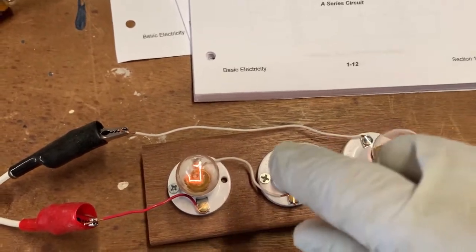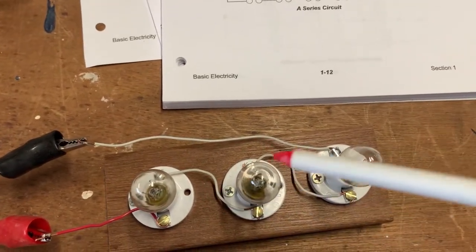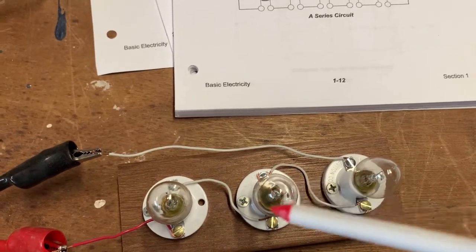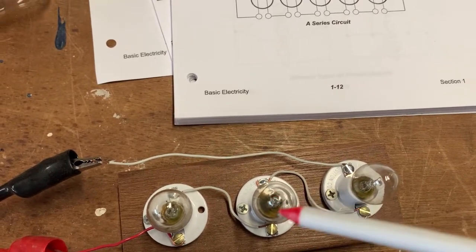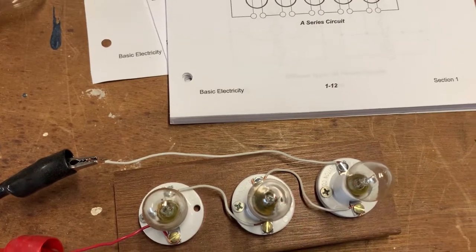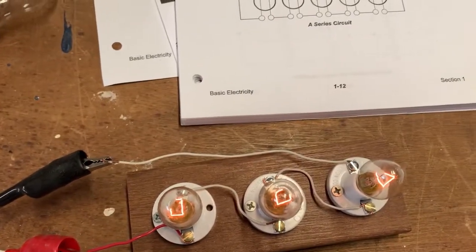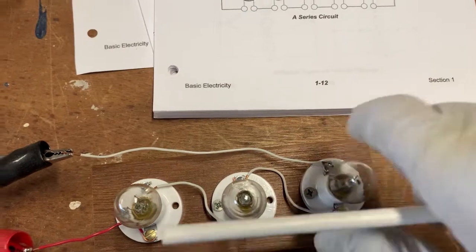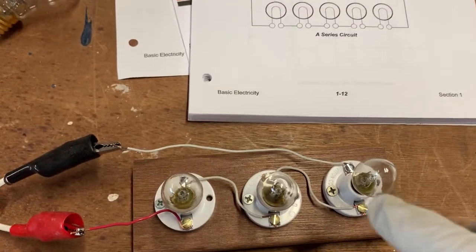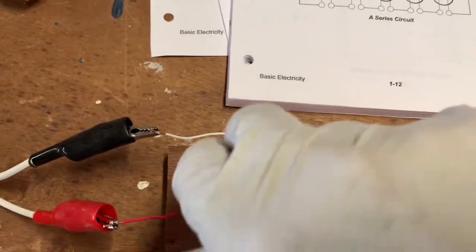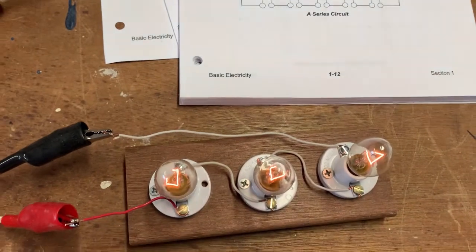If I interrupt that circuit by unscrewing one light bulb, they all go out, because now, with that light bulb filament essentially broken or turned off, I have an open circuit right here, or an incomplete circuit. I screw the light back in, the circuit is complete, and all the lights go on. And it doesn't matter which one I unscrew, it's along this chain, and anywhere I break the chain, the power stops flowing. So any one of those, and that's actually one reason why you won't encounter a lot of this type of circuit, but you do need to be aware of it.